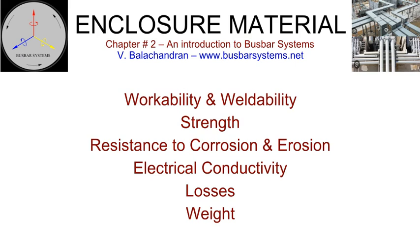Losses. All metallic enclosures of the busbar systems will generate eddy current losses, and those with steel will, in addition, generate hysteresis losses which contribute to a temperature rise of the enclosure. All international standards specify a limit on the temperature rise of the bus enclosure. Weight. The enclosure contributes significantly to the overall weight of the enclosed busbar system. Manufacturers have a preference for aluminium over steel. The lower overall weight facilitates ease of installation and lower cost of the support structure.